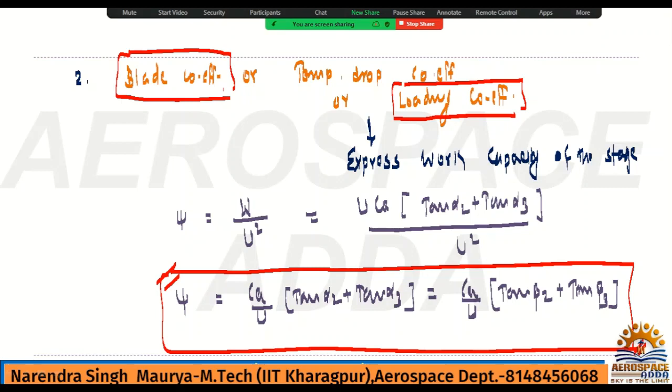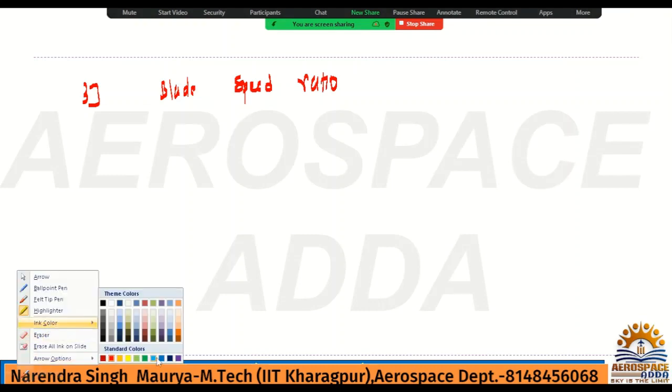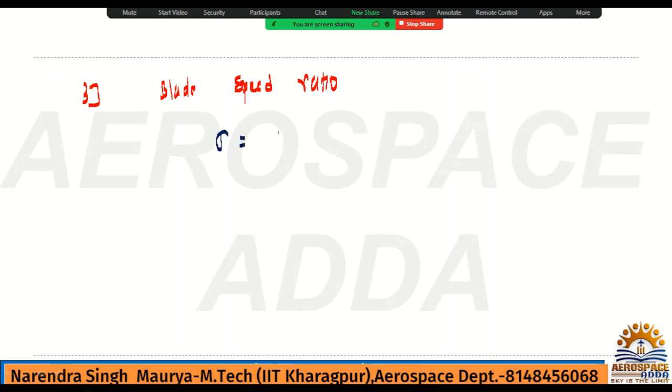So next is the speed ratio. How will you get that speed ratio? It is the ratio of the blade rotational speed to the absolute speed. Absolute speed of what? Whatever the absolute velocity is in the inlet triangle, which is nothing but C2. I will write this, it will help you in numericals. Blade speed or speed ratio is denoted by sigma, as I mentioned already. It is the blade speed divided by the absolute speed, C2.